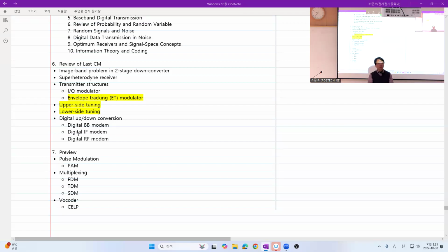Because single stage, which is direct upconversion, was costly at that time, or impossible for high frequency, high compared to that period's technology. So he found a mathematically equivalent formula. So first, generate sine and cosine with low frequency, and that was possible at that age.